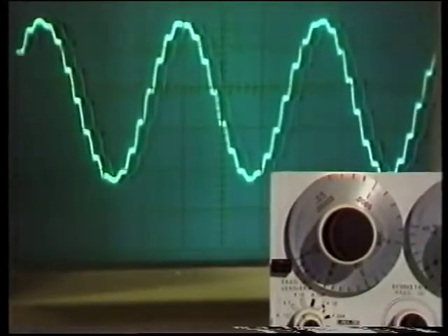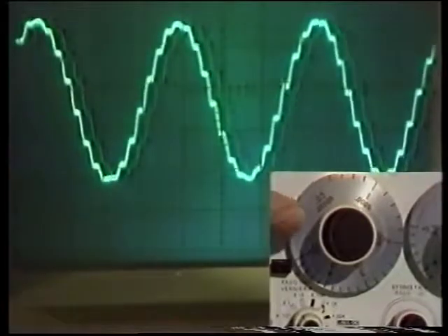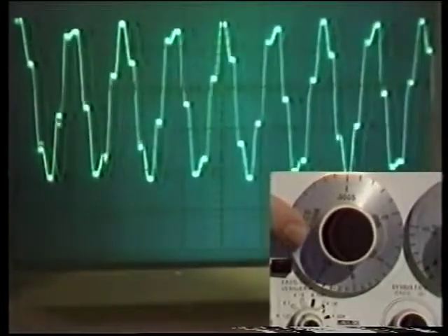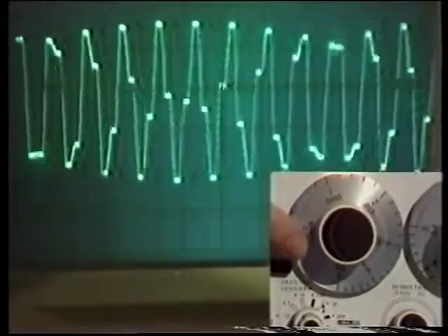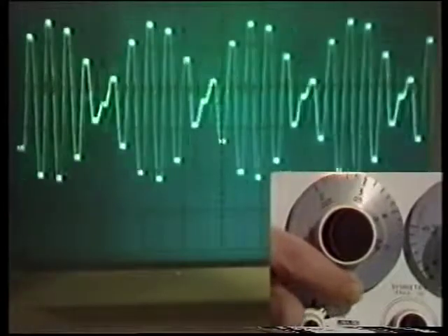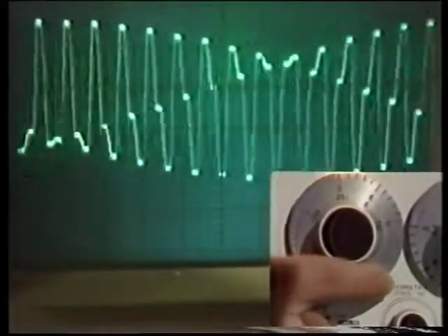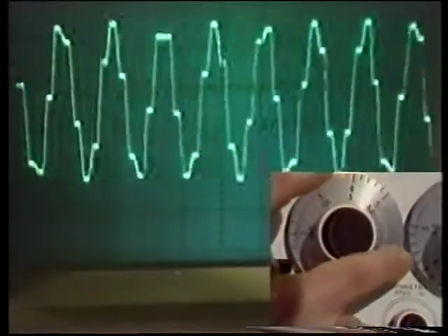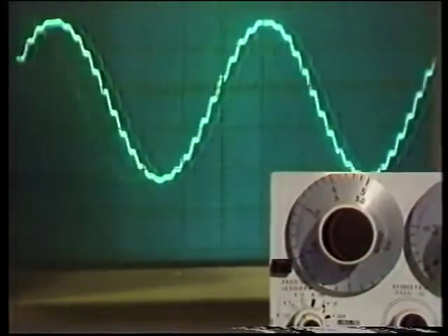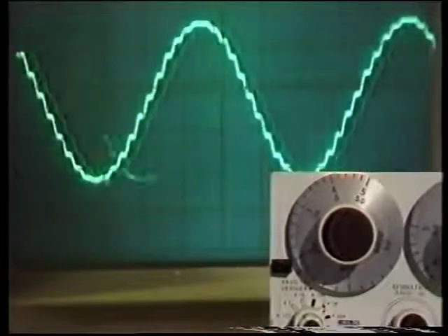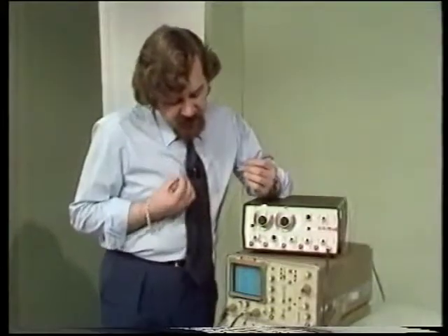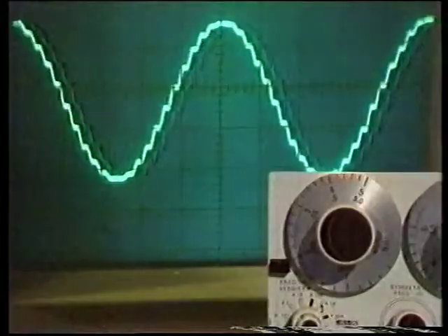Let's now increase the frequency, keeping the sampling period fixed. As I do so, you can see that we're slowly decreasing the number of samples per cycle. And then we get to a point where it's not really clear because we haven't got enough samples. But watch what happens as I continue to increase the frequency. We get to the point where suddenly we start getting more samples per cycle. So, increasing frequency with a fixed sampling period, something odd has happened. And that jittering is also due to the sampling process. And if I wanted to take a measurement, I can store it like this.